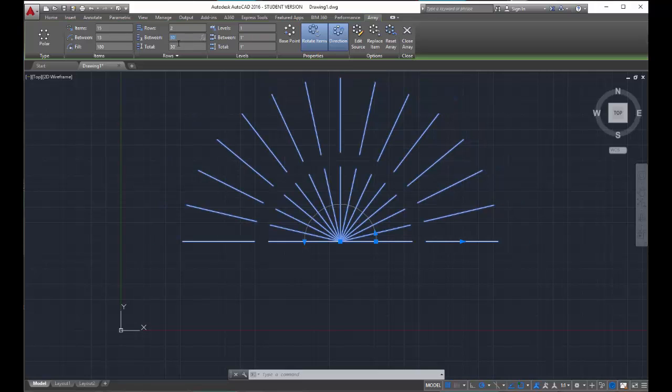It gets closer and closer until there becomes a point where it's really hard to decipher between them because they are overlapping each other. Do you see how that is overlapping? So you have to be a little bit careful when it comes to rows if you're wanting to use a row. But you can do some fun shapes and stuff. I can imagine that you could use array for all kinds of things from floor patterns to furniture design. There's a lot you can do with this type of polar array. I'm going to go ahead and put it back at 1 row.